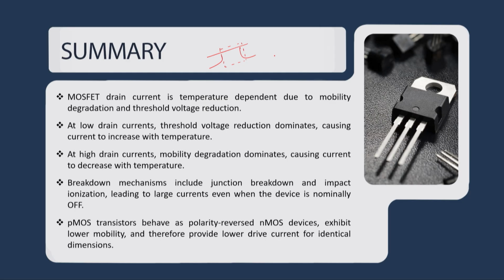Out of this we have considered a few, for example, the source and drain resistance impact, and we derived an equation and found that the overall current is altered because of this source drain resistance as IDS not including source drain resistance divided by 1 plus some beta r into (VGS minus VT), right.